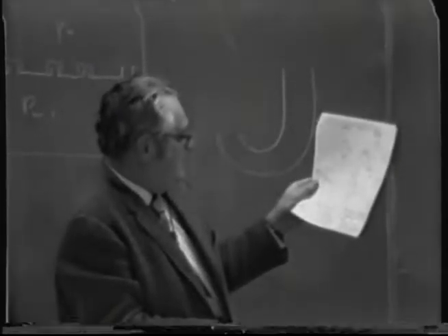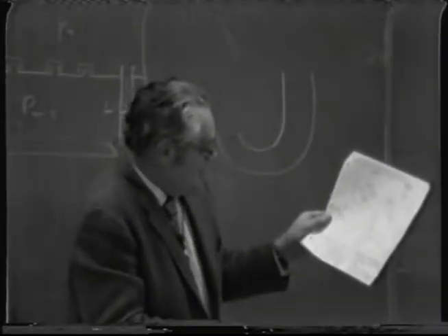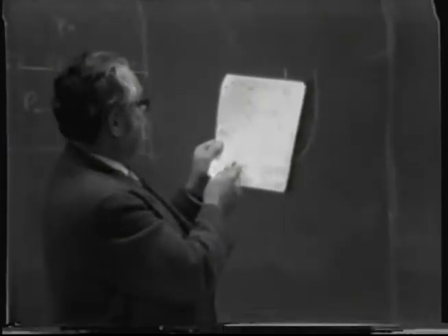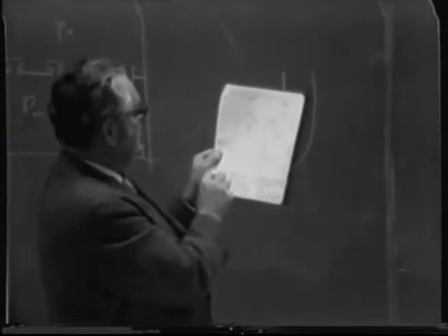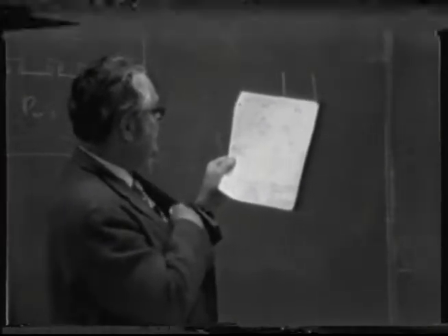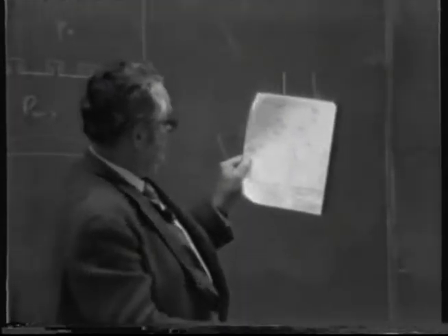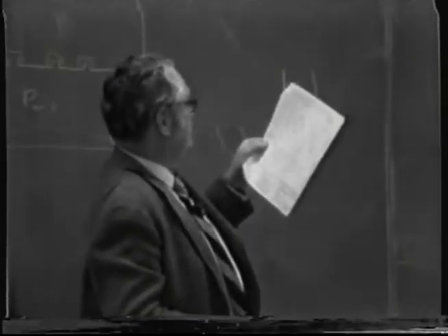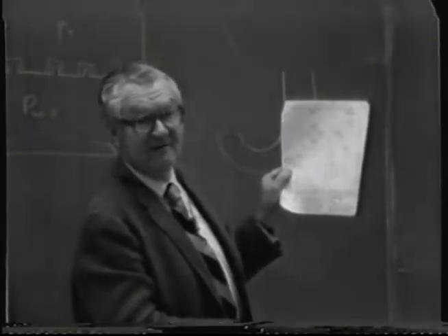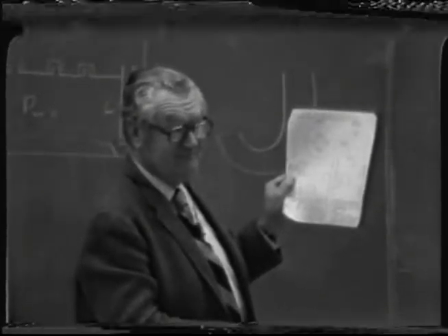The one on the left is about 60 inches in diameter, and the plate spacing was 15 inches, the overall spacing. But this J-type downcomer was, as shown here, located 7.5 inches away from the perimeter. And the discharge level of that tube was only 5 3/8 inches below the tray above. So what's the matter with that? Why would that be bad?